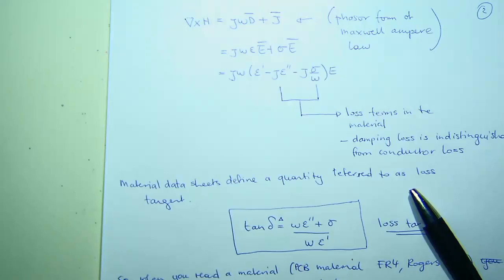So what two things does the data sheet usually tell you? It tells you multiple things, but related to the propagation of radio waves and signals on that PCB board. The material you usually use for masters level stuff is FR4. Right. I still try to use FR4 because it costs me 4 cents per square inch, whereas Rogers costs me $1 per square inch.